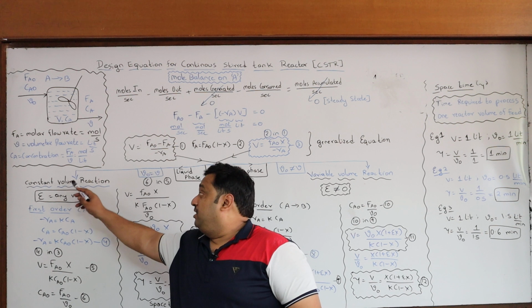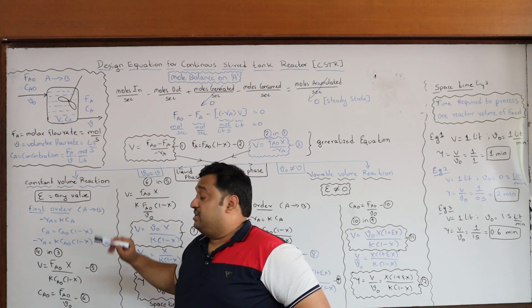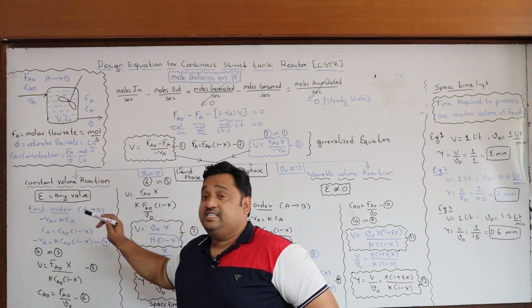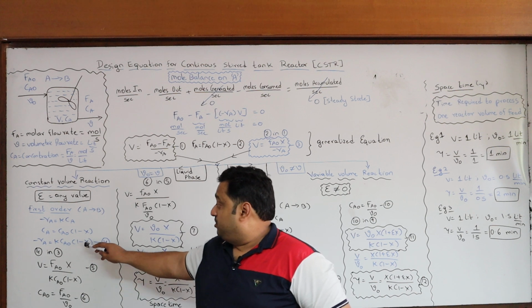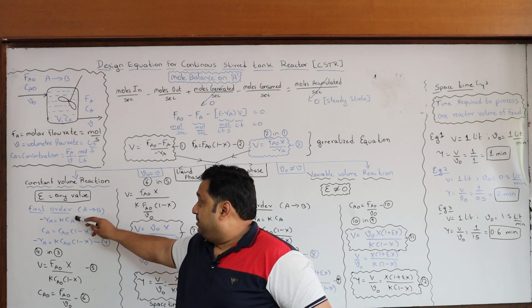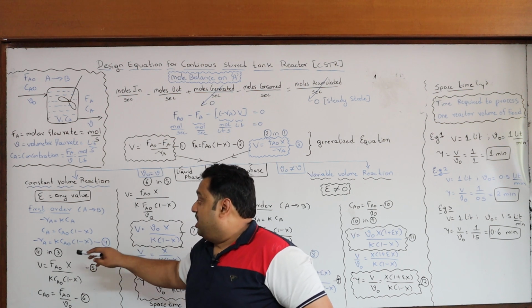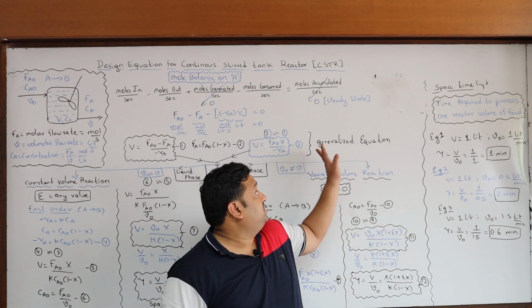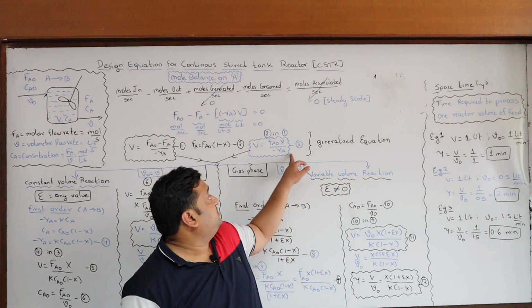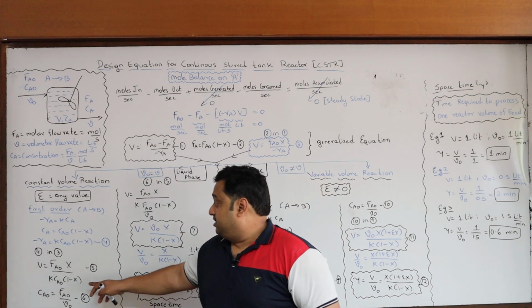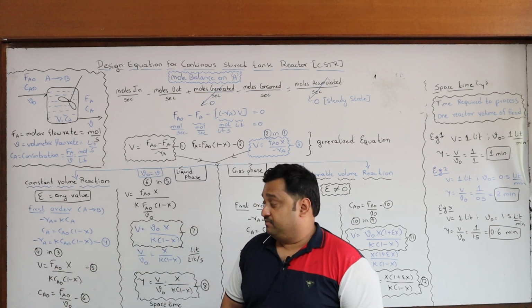I know, for example, if a first order reaction is happening in the reactor, then A gives rise to B, minus Ra equal to k Ca, you know, Ca equal to Ca0 into 1 minus x. Substitute here in place of rate, you get minus Ra is equal to k Ca0 into 1 minus x. Now use the generalized equation, substitute the value of the rate in this generalized equation, and you get V equal to Fa0 into x by k Ca0 into 1 minus x.